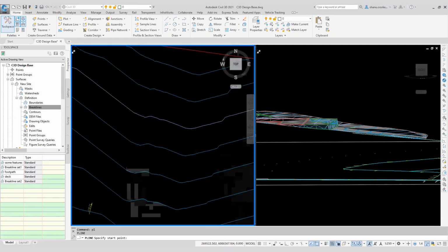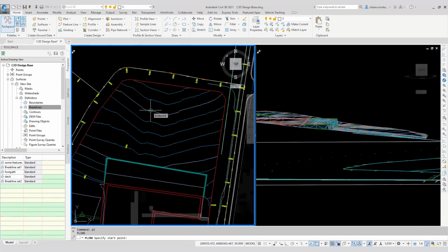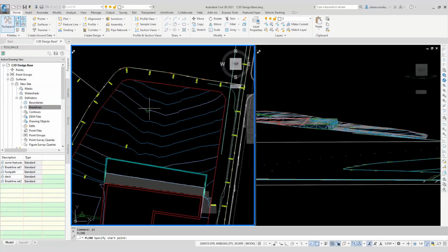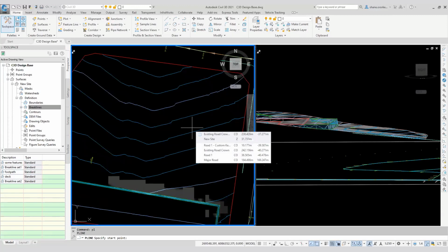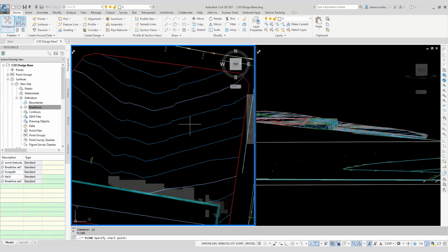If you have something that's sort of a structured rules-based shape, a curb, a retaining wall, detention basin, then you can use grading to automate the connection. So rather than using stepped offset, you can basically say, hey, do a rule from here to here with these slope behaviors or height difference behaviors.